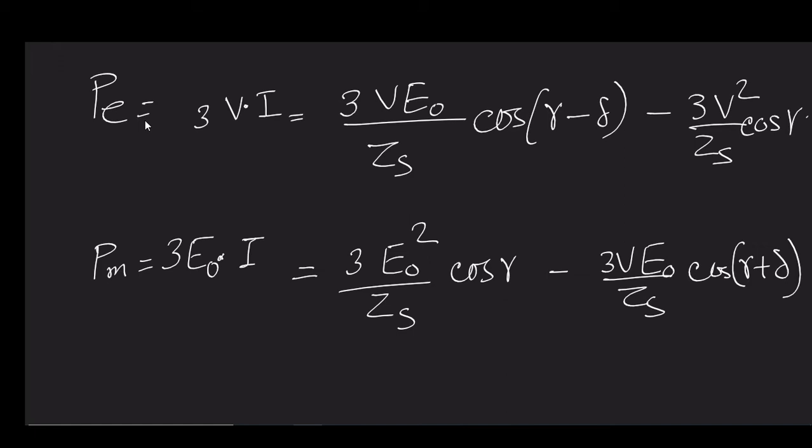But what actually governs your machine core loss, a very important thing, is the terminal voltage and frequency of the machine. Terminal voltage, if you add the proportional amount of armature circuit drop, will give you a value of your induced EMF, V plus IR.